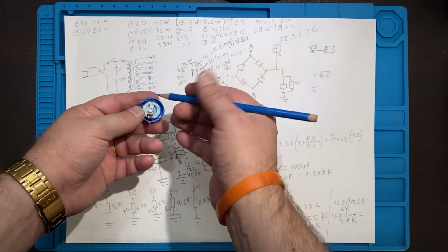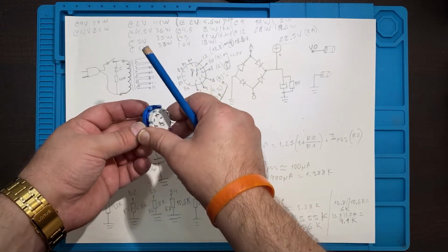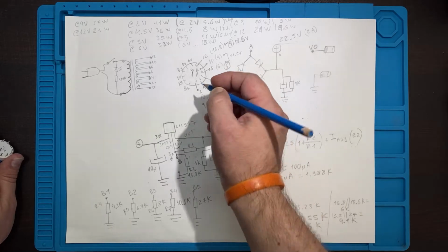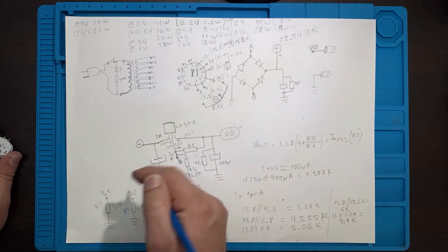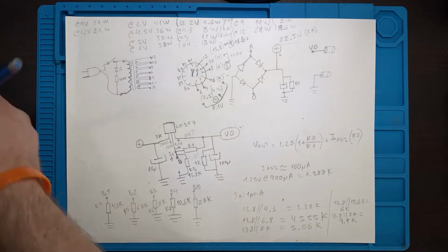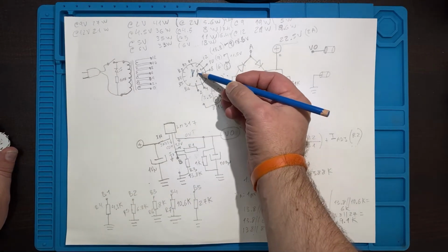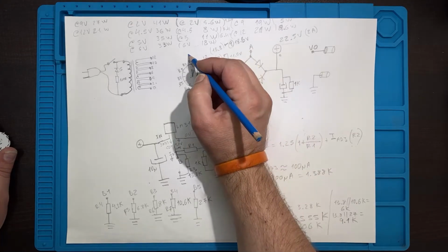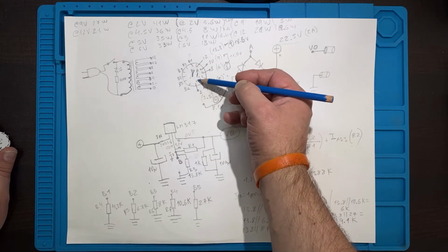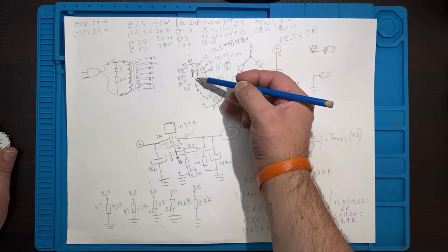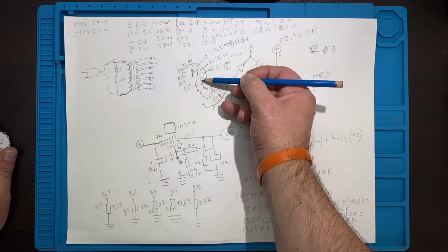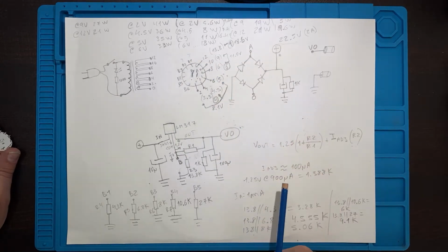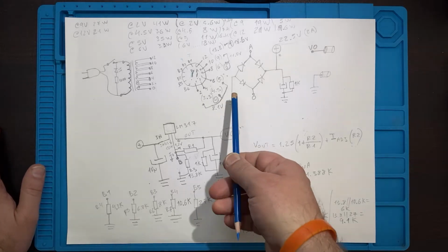It actually has another contact here. So the way this rotary switch works is a bit different. There's no B, and when one is selected, A, and in this case B1, which would be 7, is connected to A. 7 and 1 are connected to A. When 2 is selected, 8 and 2 are connected to A, and so on. So that's not going to work, right?